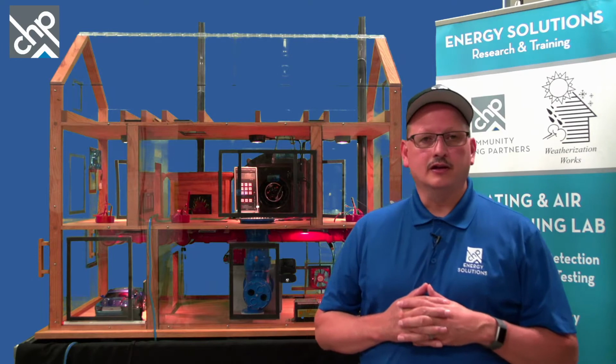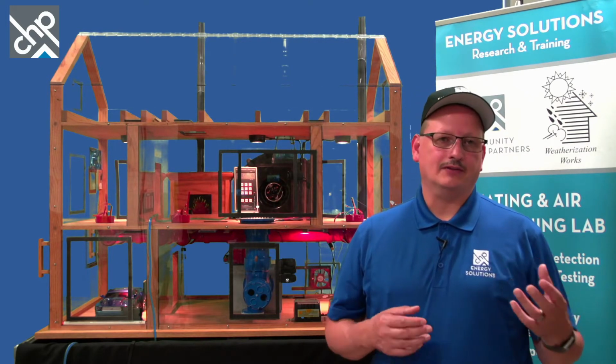You also have to think about pressures, because pressures create airflow. If you've got a hole and a pressure difference, you can get airflow. And that air might be moving combustion gases into the building, car exhaust gases, or moisture from the outside. So if you make the house tighter or leakier, the pressures change and affect where the air is coming from.